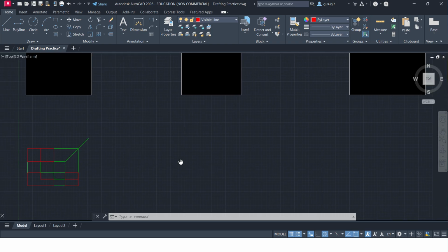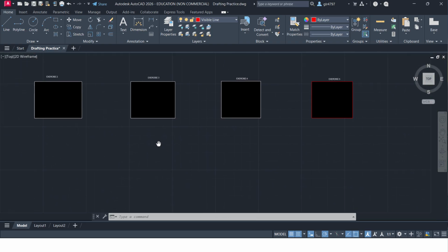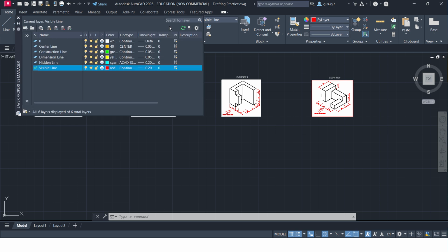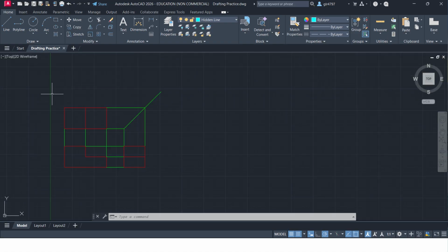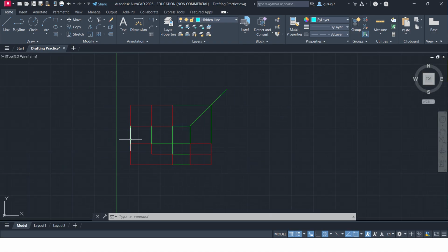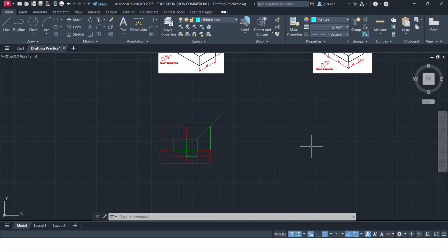Just note as well, for exercises 3, 4, and 5, you will have to use the hidden line. This is what it looks like. It's dotted, it's dashed. You're going to have to use that strategically, okay? But for now, this is what we're looking for. Your construction lines are set up, your reflection lines in place, your visible lines are there, everything's the right dimension, and that's basically it. And then for exercises 3, 4, 5, you have your hidden lines in the right places.